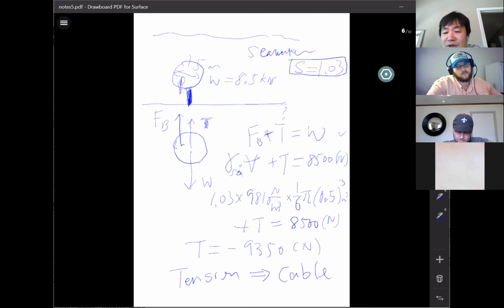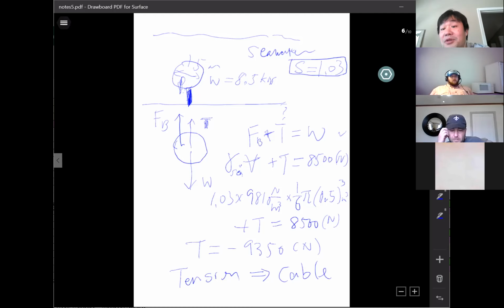Josh, you're totally right. You said it depends on if the density is heavier or lighter, right? But it has to be comparing to the density of the object. We don't know the density of the object. It directly gives me the weight. Okay, so you can back calculate the density of the object based on the weight. Yeah, so I just made that observation looking at the free body diagram on which way to put it. Yeah, which one is exactly bigger? Okay, see, this is a simple example using the buoyancy principle here.